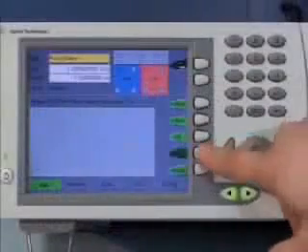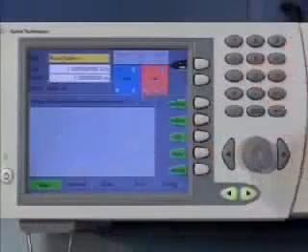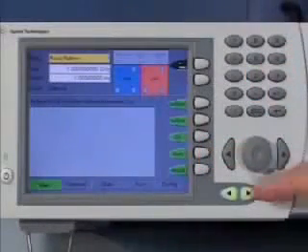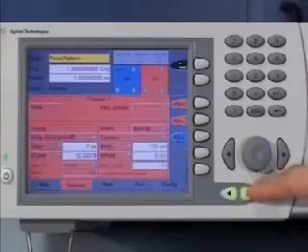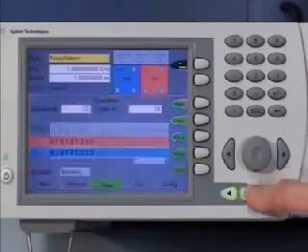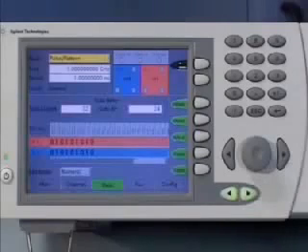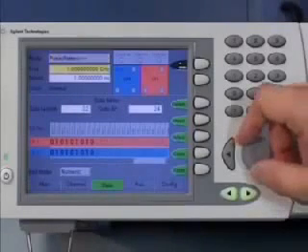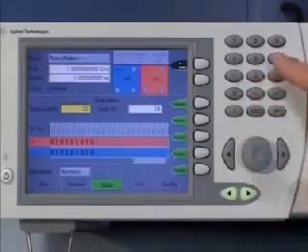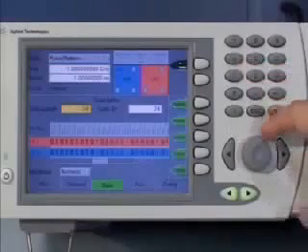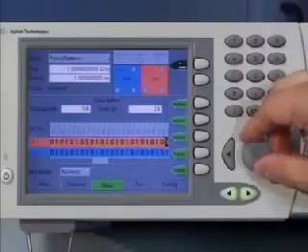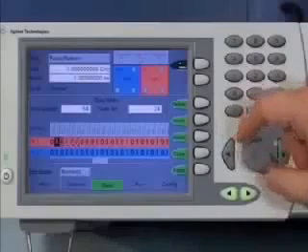The submenus can be accessed on the lower part of the screen. For example, restoring and saving settings, or modifying any output channel settings like the data pattern settings, etc. The data pattern submenu provides access to all pattern settings, including the length of the pattern, and also allows to directly change the selected data pattern.